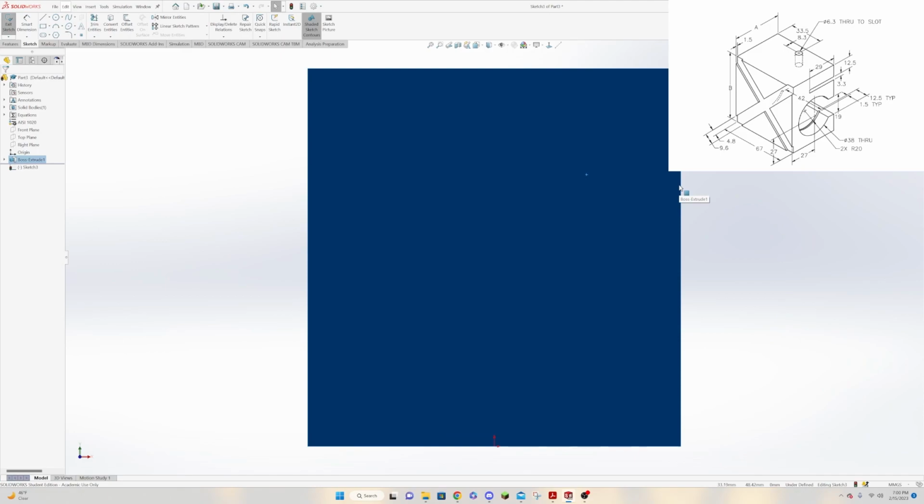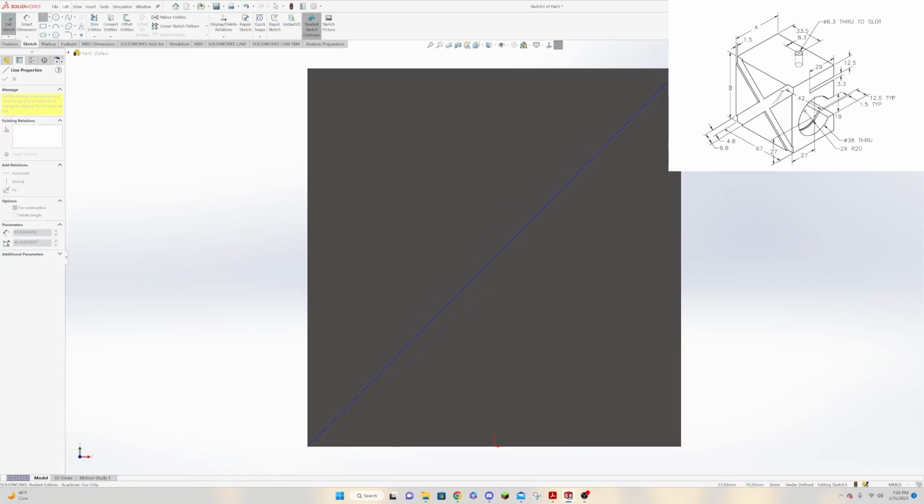It's more that from this center line to the one edge would be 4.8 if we were going perpendicular, and our gap between the two edges is 9.6. And it just doesn't look super intuitive the way the drawing is showing those lines. The way I did this is I chose to draw some construction lines here, and I went point to point, push escape, and then point to point, push escape. Once again, there's many ways that you could do this. I just found that this was the quickest way to do this.